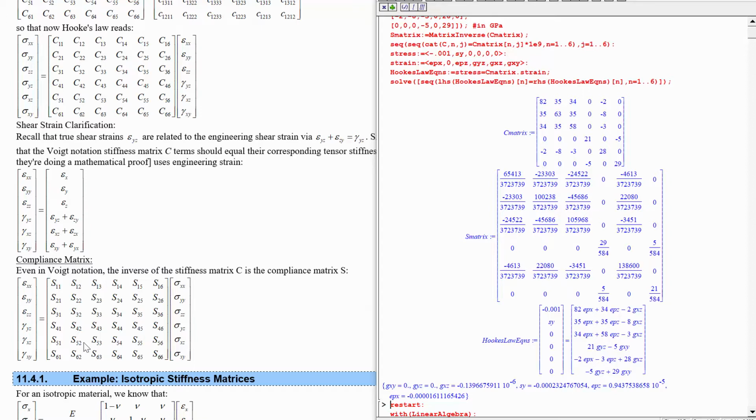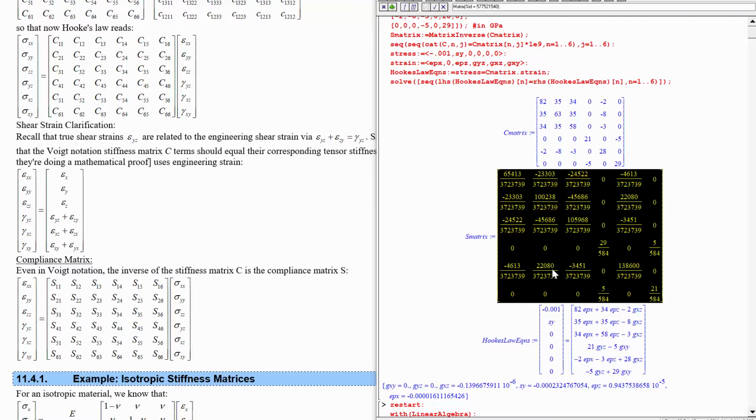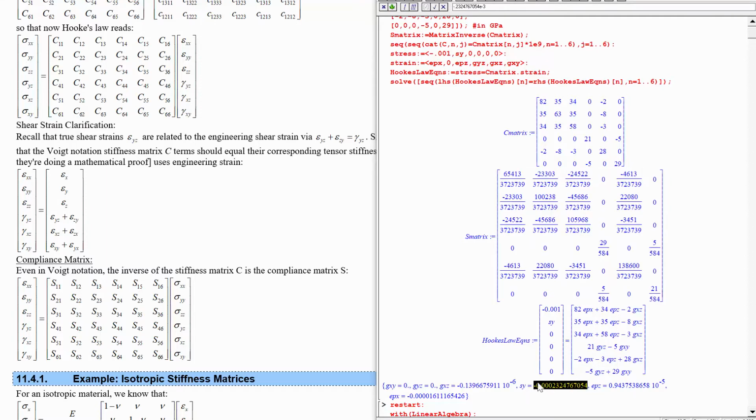And that tells us that we should have, from the negative y stress that's showing up, this is a little bit complicated. We have a negative y stress and this component's bigger, but the x stress that we applied was a lot larger, so that means that the x term will probably dominate. Yeah, this is only 5 times as big as this. Oh, but wait a minute. This is also only a little bit less than 5 times as big as that. So it looks like we're going to be getting an XZ shear strain, but it's a little bit complicated to tell whether it should be positive or negative because these two terms are generating differently directed things towards it.